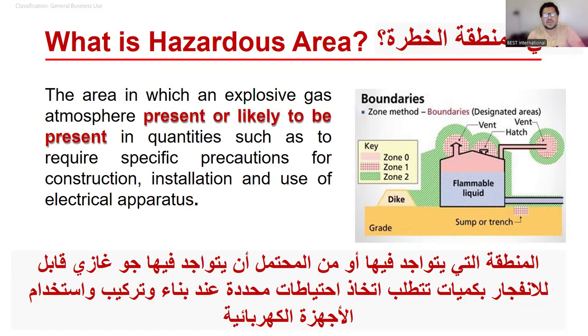Likewise, there are certain rules. If you are working in an Aramco network, you can see all these limits mentioned on the permit, whether it is the EOLB, equipment opening line break permit, or the hot work permit, cold work permit, or confined space entry permit. These limits are well mentioned. What is the normal oxygen level? 20 to 23.5%. What is the H2S? Below 10 ppm. What is the permissible limit? At 10 to 20 ppm, SCBA is mandatory, and at more than 20 ppm sometimes Aramco will not allow you to work. If you still want to work, it would be a short exposure, along with the approval of the leadership. Sometimes Aramco will not allow you to work even if 1 ppm of H2S is there.